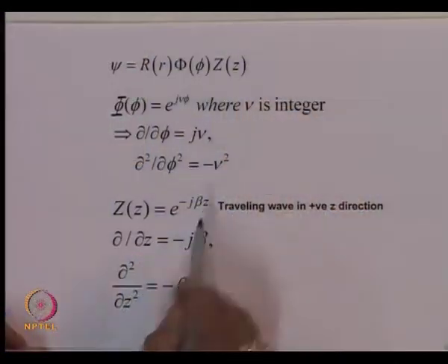Or in other words, we have a wave which is going to propagate in this structure, and if we assume that this fiber is of infinite length, there is only one wave which travels inside this fiber. And we know that this travelling wave behavior can be expressed by a function e to the power minus j beta z.